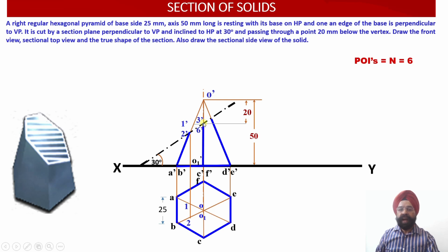So this way I know the height, that is, this height is there from the base, and then I am going to take this to the right so that I can look from this angle. The moment I take it to the right, I have obtained one point of intersection on the slant generators O dash A dash and O dash B dash. Now this radius I am going to transfer in the plan view, and in the plan view, on which generators will this be transferred? Again on OA and OB.